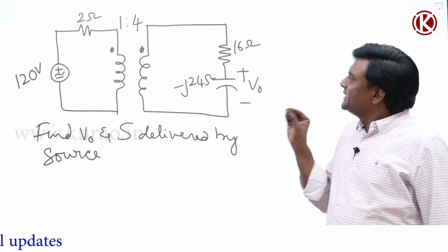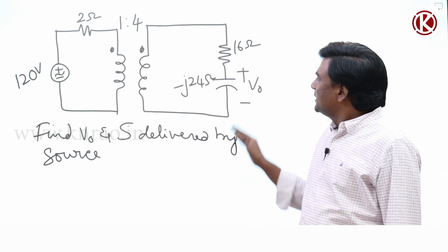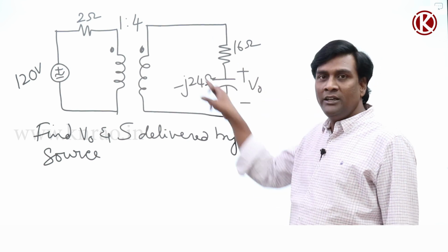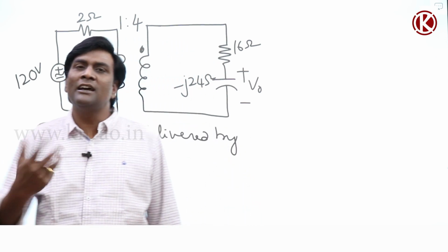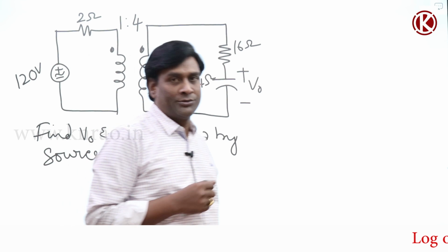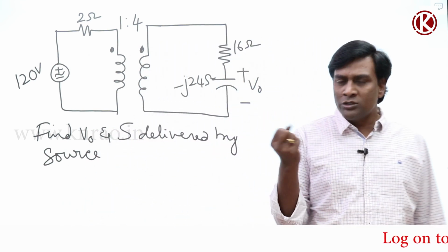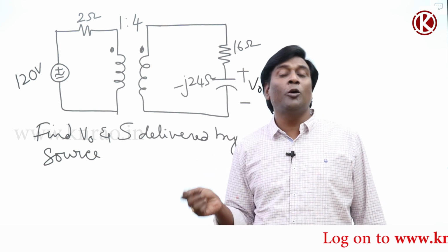If I think of this as a machine transformer, then definitely I will ask about the load. Normally, what is the load, lagging or leading? Predominantly we are going to have lagging loads. Why? Most of the loads are induction motor loads, so inductive dominated loads.